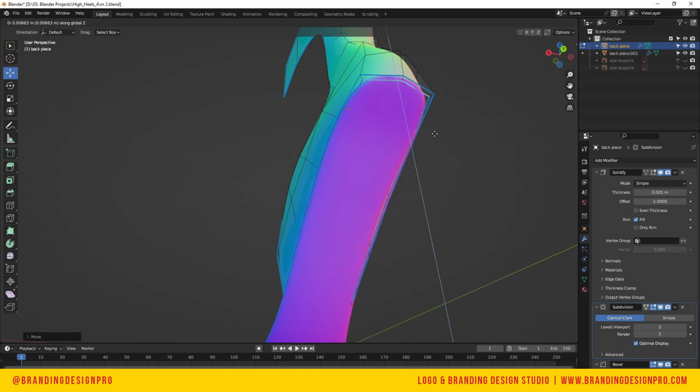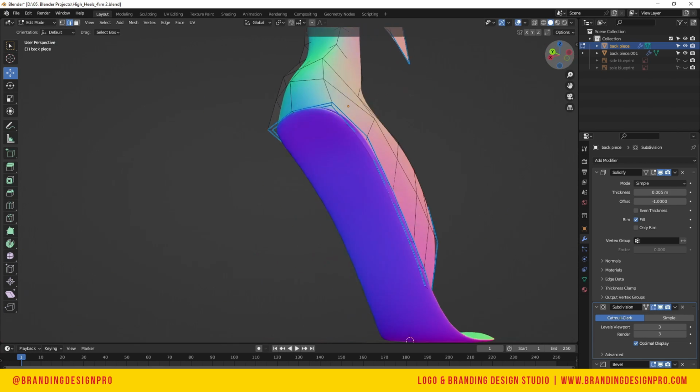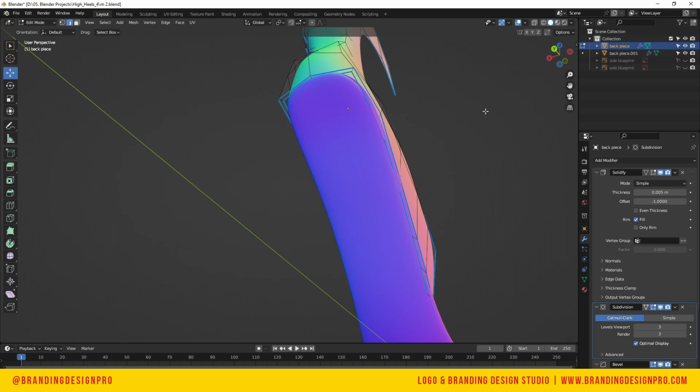So you can hit G and Z to make life a little easier and moving those edges, having more control. Select that side and GX and then GZ, left click, and then same thing, just adjust these shapes, adjust the edge placement.